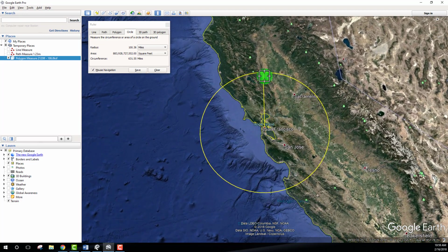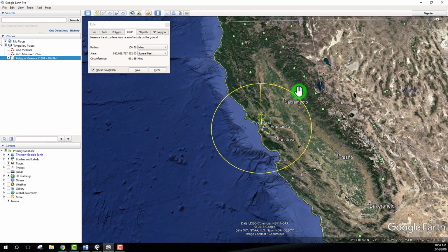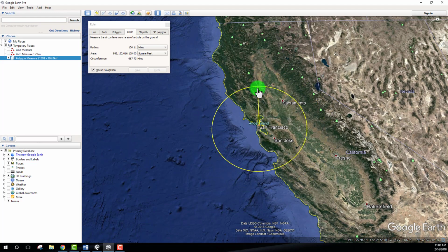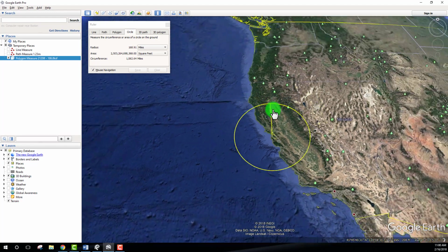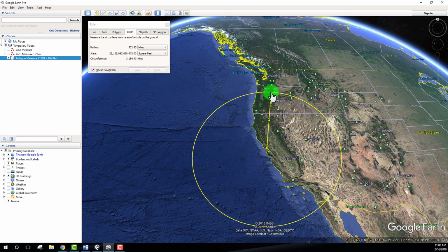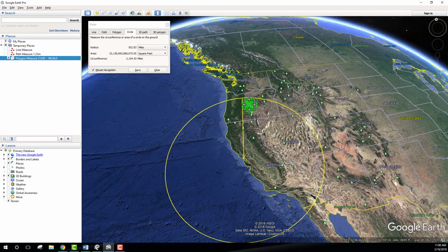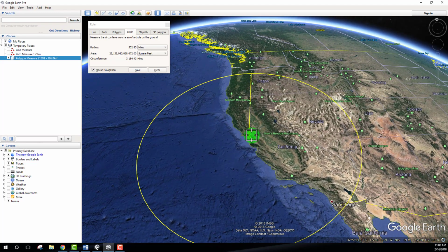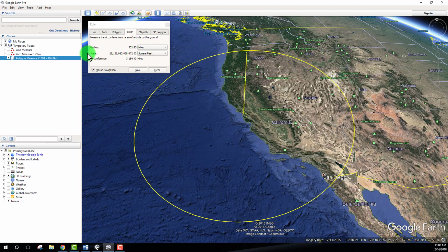And so this gives us essentially what a 100 mile radius looks like in this case. I can click and snap that, and then that's essentially stuck in that view. I can always take that, and by grabbing that node right where this point comes out, I can adjust it as well. So say if I wanted to understand what 500 miles looks like, I could do that. That's really useful for a real quick understanding of different radiuses or locations from a specific city or location. At the same time, it's going to calculate the area for us. So what is that, like 22 trillion square feet? Probably go to acres, or maybe miles is more appropriate.